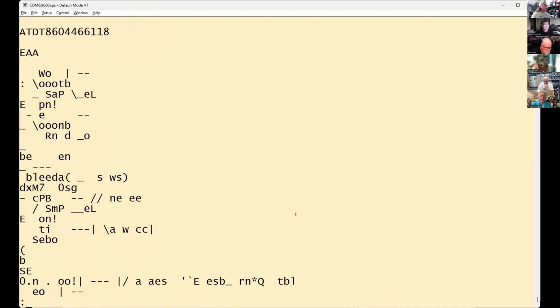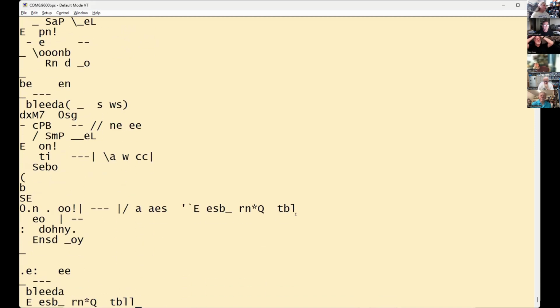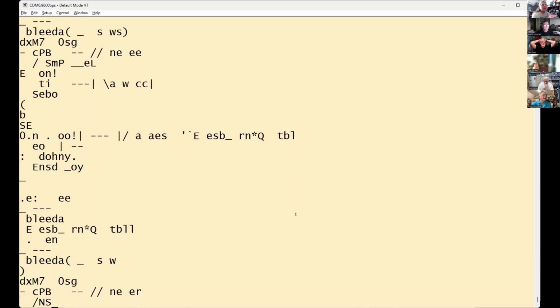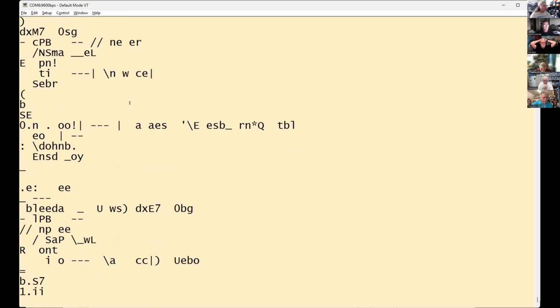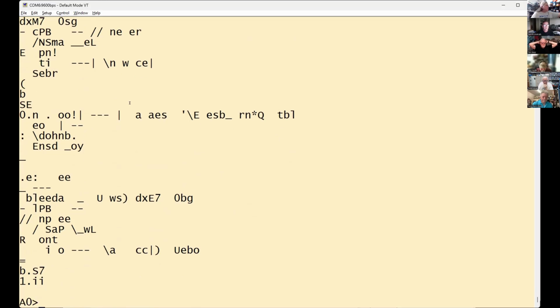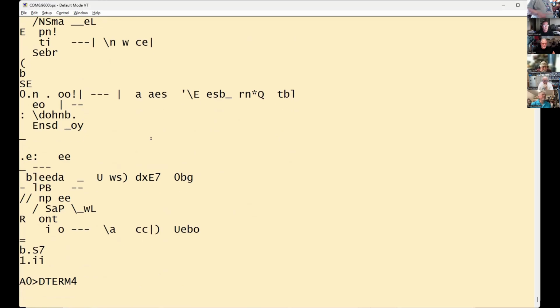Yeah. So is there an option with the modem to tell it not to echo responses from the AT commands? There was something years ago. Yeah, the AT command set is huge. But here's the thing. This is tied to port 12 and 13. Now let me exit all this. Walt, you're definitely receiving characters. I don't know why the modem's behaving the way it is. That looks like a modem config issue.